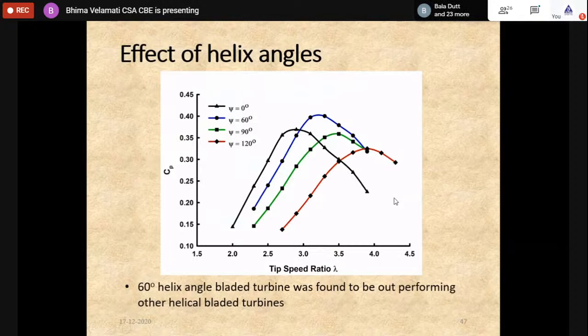So here again, we did a turbine size which is more what you call commercially viable, not a laboratory scale. The turbine diameter is 2.7, height is 3 meters. 3 meters is like 2 times the height of a person. Typical average height is 1.6. Can you imagine? So given that, we have done for 3 helix angles compared with straight blade.